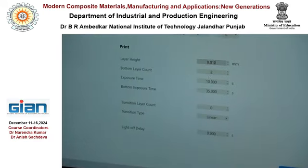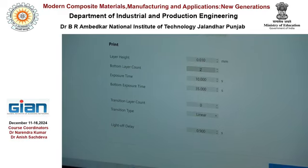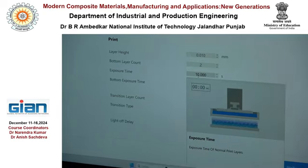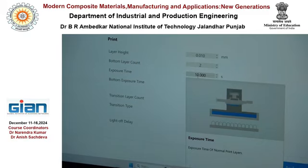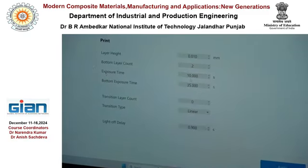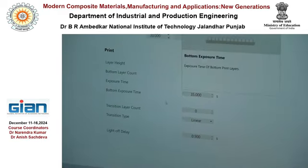The count number is 2. Exposure time is how many seconds the UV light should fall on that layer, that is 10 seconds. 10 seconds is the normal exposure time. For bottom exposure time it is 35 seconds.